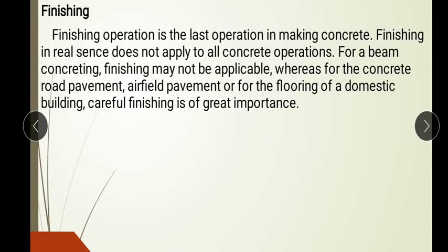Next one is finishing. This is the final thing which we need to do after the curing process. After 28 days and removal of every shuttering or wooden material used to support the fresh concrete, we need to finish the surfaces so that they look good and are in a proper manner.